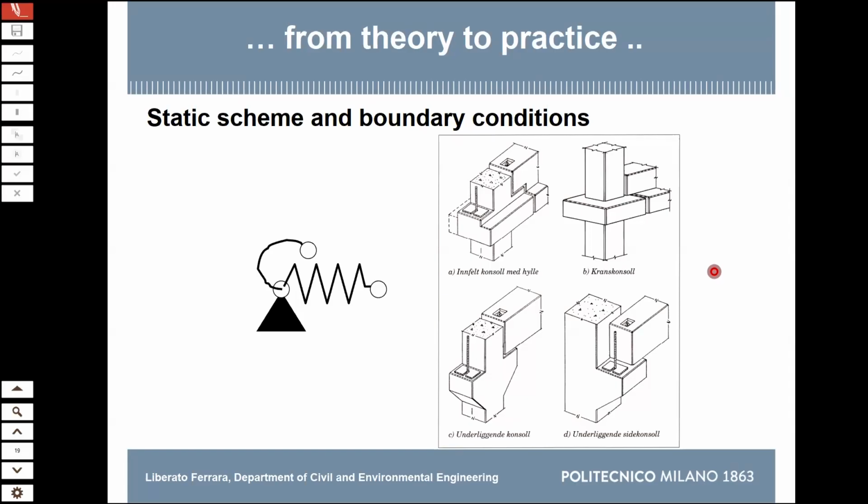The test that we have seen this morning, for example, can allow you to quantify how far that connection, which is the beam supported on a corbel with a dowel, is fully hinged, or you have to put into that some stiffness. Because you know, what is the outcome of this? Well, your stresses inside the elements can change.